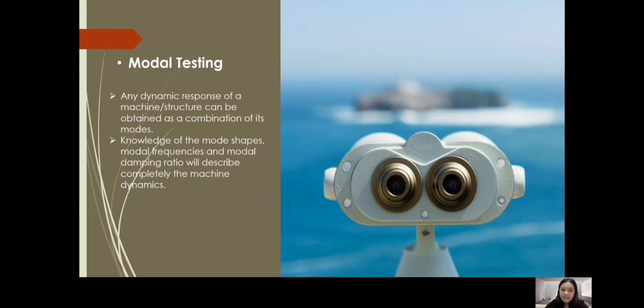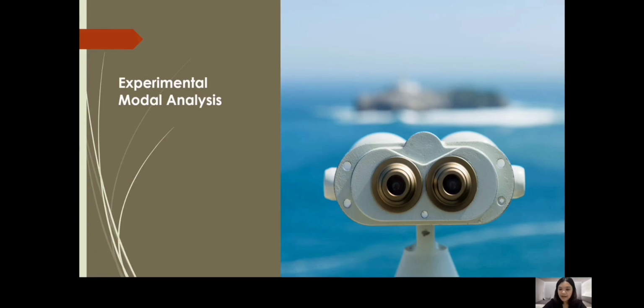For my next topic, let me discuss experimental modal analysis. Experimental modal analysis is an effective instrument for describing, understanding, and modeling the dynamic behavior of a structure. It can be carried out both to determine the natural frequencies and mode shapes of a structure and to verify accuracy and calibrate the finite element model.